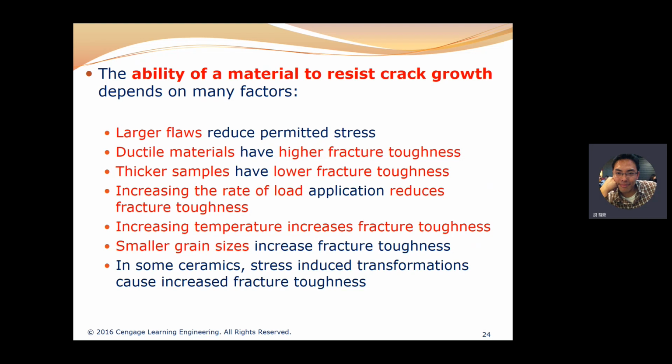The smaller grain size has more grain boundary, right? And that longer grain boundary, or smaller size, increases fracture toughness. Especially at the crack tip, you can think of it this way. If we have a smaller grain size, what does that mean at the crack tip?